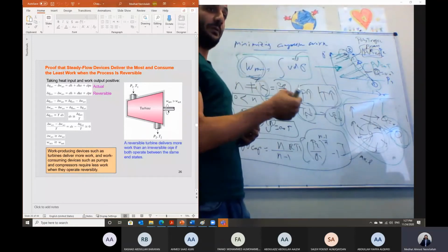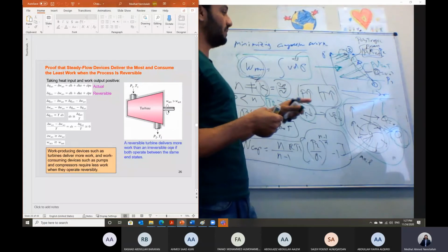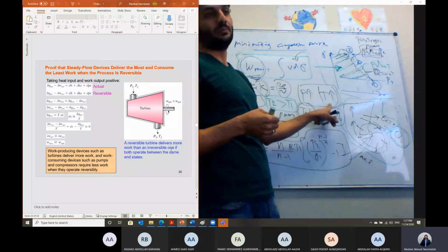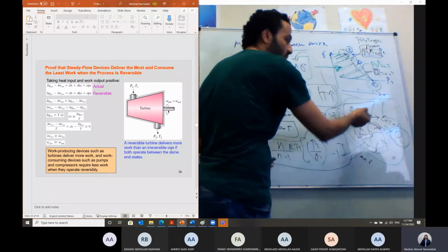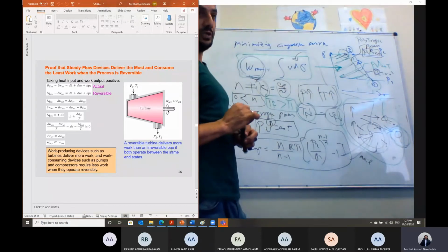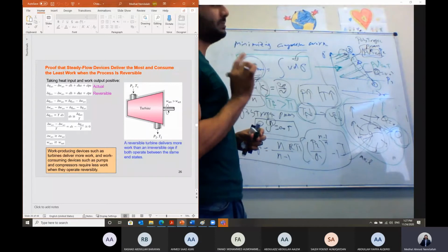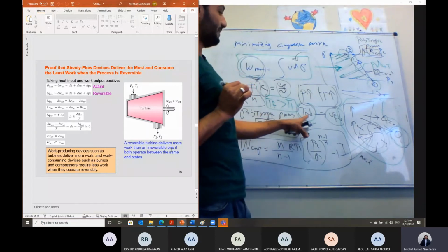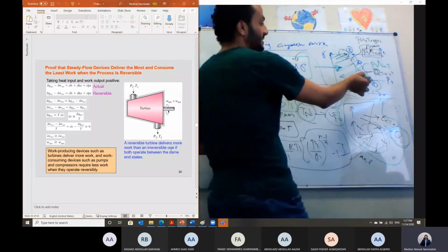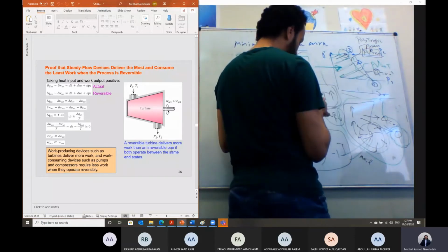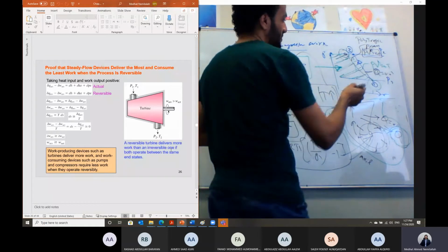The temperature will try to rise when we increase the pressure, but I will be cooling down the compressor using a water jacket, so the temperature will be fixed. That means the final temperature will equal the initial temperature, and in this case the final temperature will be the minimum. So that should be the final.